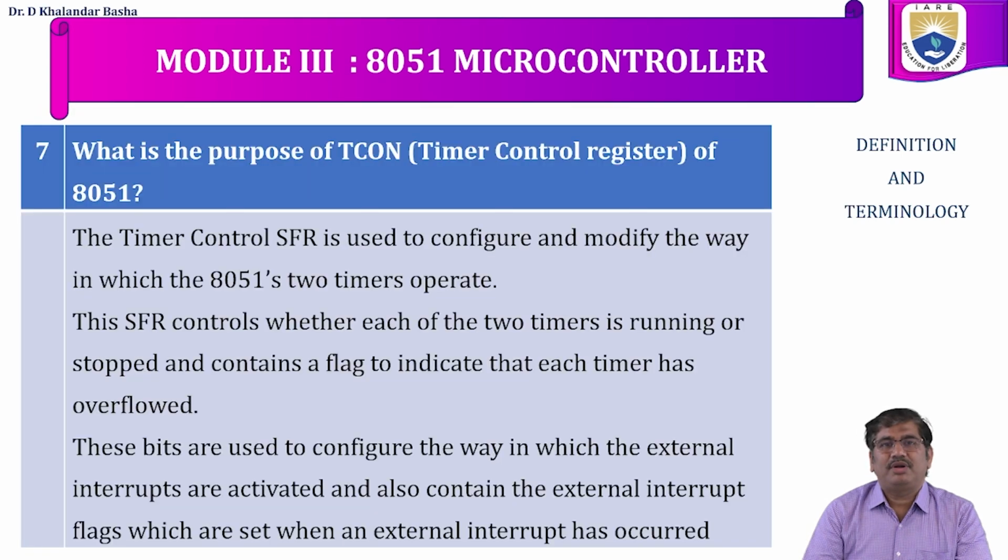Next one is, what is the purpose of TCON register, that is timer control register of 8051 microcontroller? In the 8051 microcontroller, we have two timers which we can configure as counters also. To control these timers or counters, we have the TCON register. The timer control SFR is used to configure and modify the way in which the 8051 two timers operate.